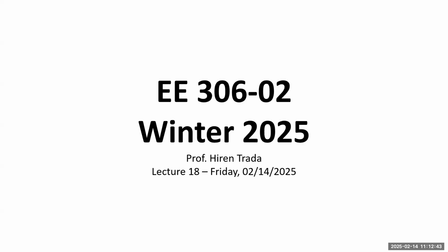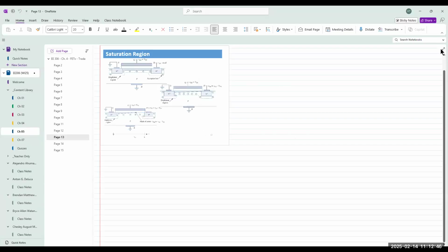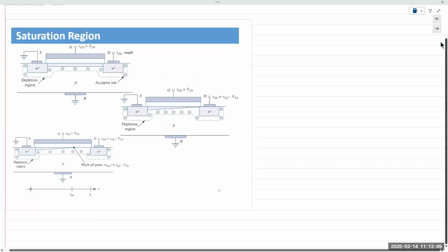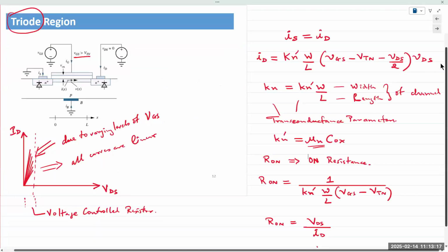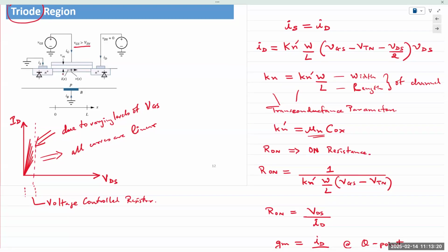All right. So one last page in FETs was the saturation region before we get to BJTs. So we saw in MOSFETs how we can apply a voltage at the gate. We obtain a channel right below the gate. When you apply a voltage between the drain and the source, you have current flowing through that channel, right from that channel. That was in the triode region or the linear region. So you have free current flow going between the drain and the source.